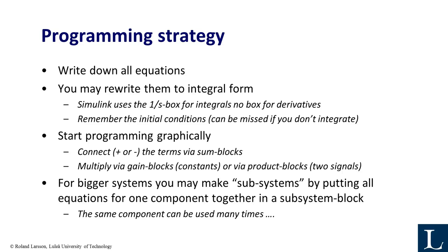And remember the initial conditions. You may remember that I missed that in part 2, where I made my Simulink program. When you integrate, you must take the initial condition into account, otherwise you get wrong absolute values. And then you start programming graphically.